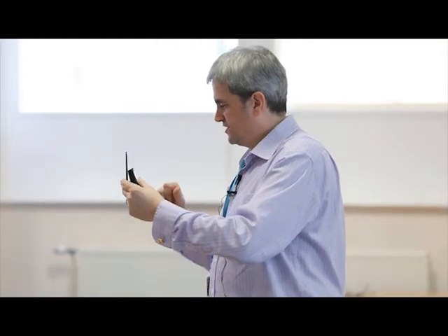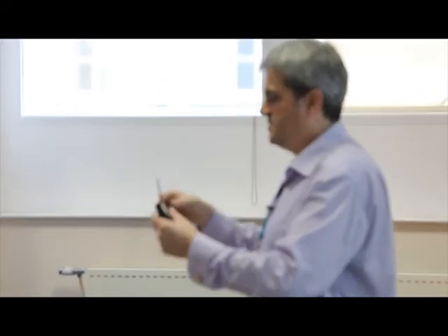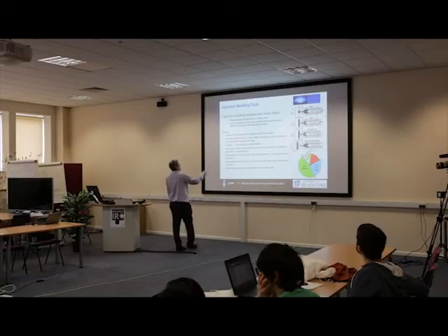But if you look on the back of the part here, where we have this rib junction and another thicker section here, you will see a slight indented area, which is caused by this shrinkage process, okay? So it's quite a nice visual indicator of what's going on. So they're the two main parts of the process.